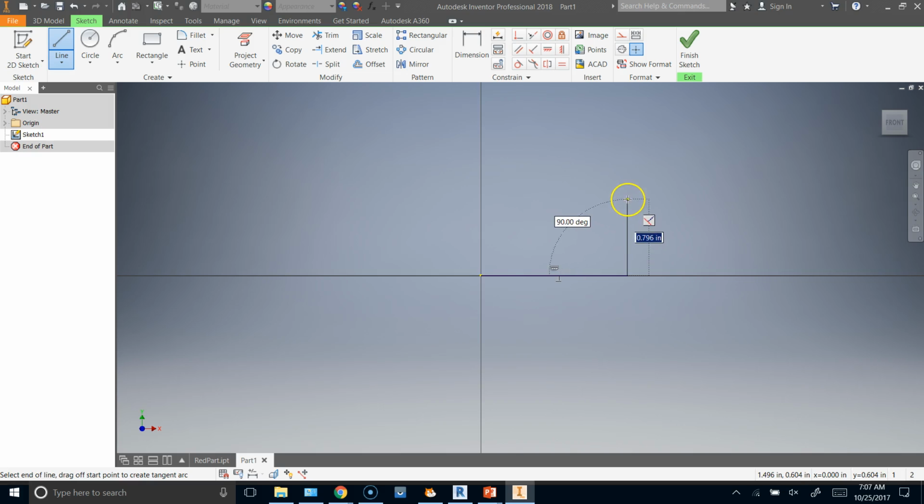I'm going to come up about 3/4 inch because we're 1 cube high. That's close enough, 3/4. I'm going to come back in and you're going to see a couple of things happen. One, as I hover over the... oops, I clicked accidentally. I'll undo that click. Go back to the line tool, and you can always resume lines by coming back again. The green dot shows that you're connected to an existing point.